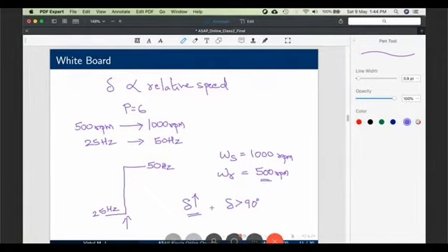We call it machine falling out of step. The machine will just stall. It will not work as a motor anymore. Is the concept clear? So what I'm trying to say is that if you increase the frequency in a stepped manner, there is a definite possibility that the machine can go into instability. This is one drawback of true synchronous mode of operation. Instability is an inherent feature of true synchronous mode.